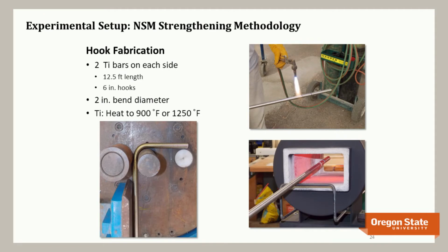So you heat it with an oxyacetylene torch, and as you get it hotter, it starts to change color. When it turns that nice golden straw color that you see in the lower left, you bend it, and that's our conventional rebar bender, to put the hook on. And you can do this in the field.